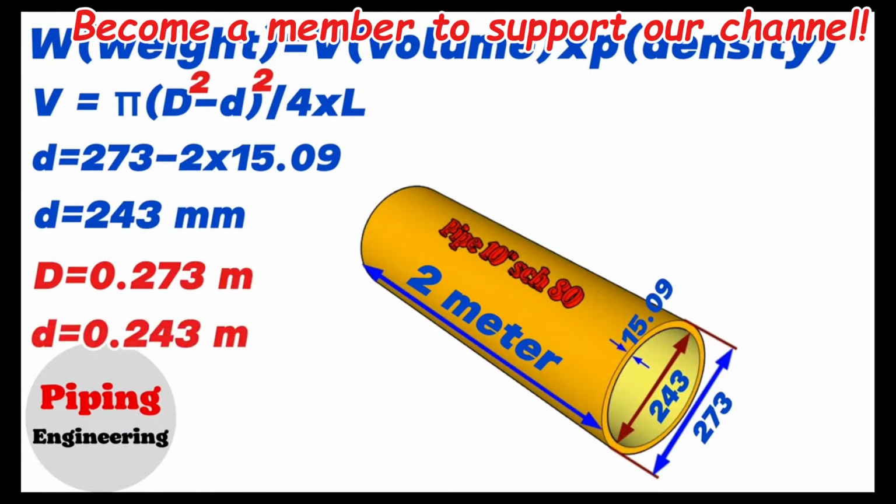Now let's write this information we found in the volume calculation formula. The volume of the 10-inch pipe in our example will equal pi multiplied by, in brackets, the squared 0.273 minus the squared 0.243, divided by 4, multiplied by 2 meters. Using the calculator, we find that 3.14 multiplied by, in brackets, the squared 0.273 minus the squared 0.243, divided by 4, multiplied by 2 equals 0.0243. So, the volume of the 10-inch pipe in our example equals 0.0243 cubic meters.